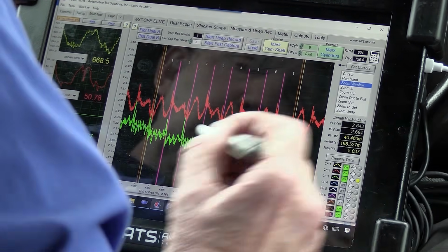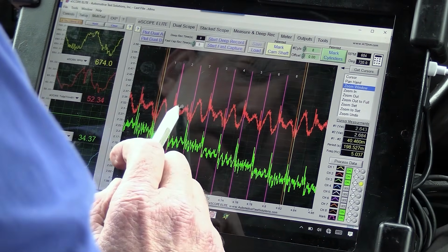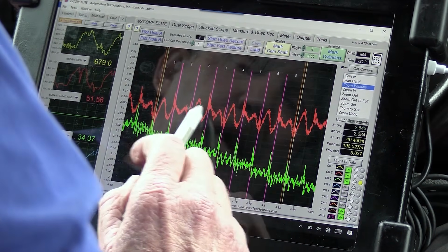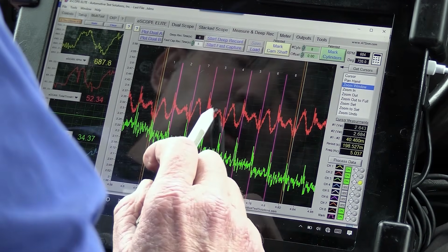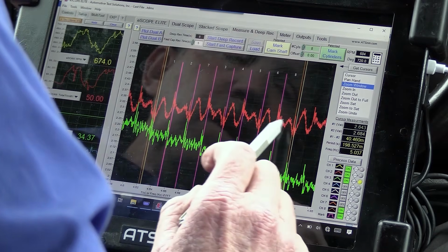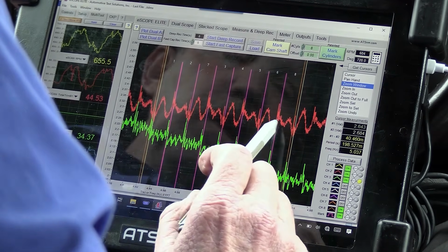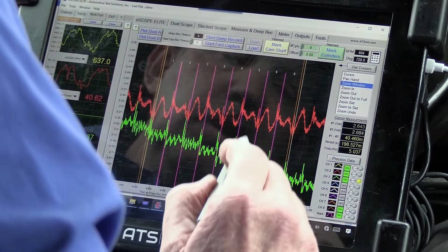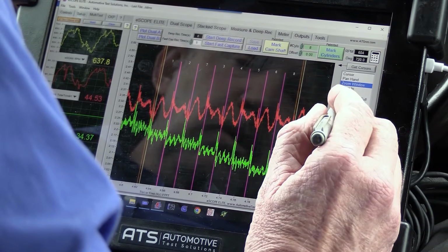This is when the car is having a problem, and we can clearly see it because we're flat, flat, flat, and flat, and that's what we've been chasing, is why this is flat. Now we know why it's flat. The jack shaft chain has got to be stretched. Something's wrong with that jack shaft chain. That's what's wrong. So we can clearly see this here. Okay, let's go back to where we were.